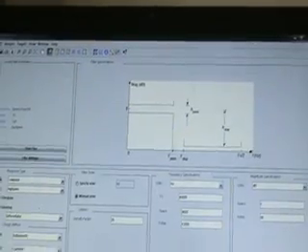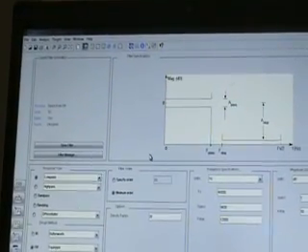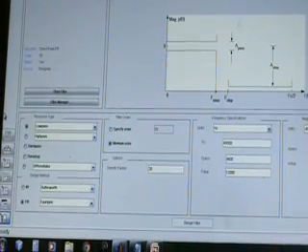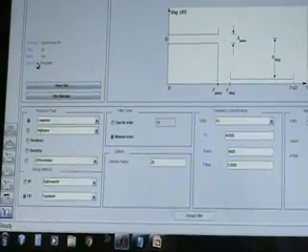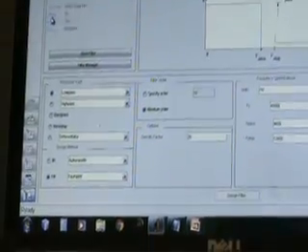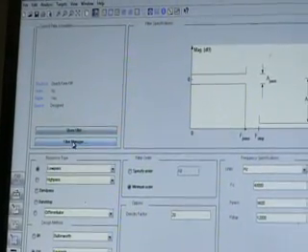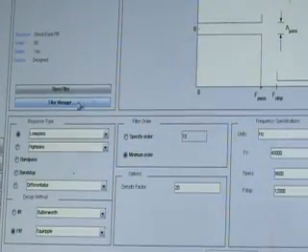This is the FDAtool. The first block is the current filter information, second is the filter specifications, third is the design panel. The current filter information block in the upper left displays filter properties such as filter structure, order, whether the filter is stable or not, and the source of the filter. It has a filter manager in which we can work with multiple filters at a time.